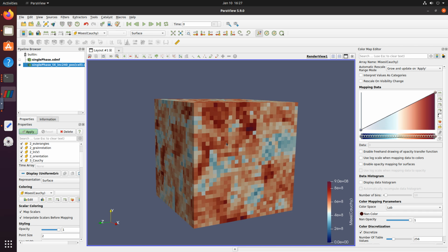But if you're only interested in the global results, then what I always do is I define a very rough geometry of very small size, so I can run very fast simulations and at least quickly get the global results that I can then use to compare or calibrate. And then we have techniques, for example the minimum size of the geometry, the minimum number of grains that are required to at least reach that isotropic level.